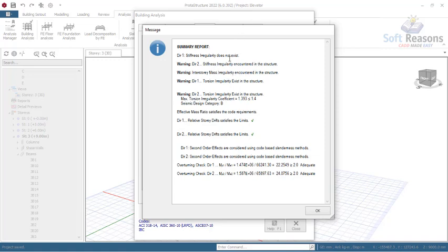Now, when you are seeing most of this warning, it is because of the way you model some of your structural members and how you incline them. As you can see in the structure, I have some inclined columns, right? Columns that are being inclined. So that is why you see this. This is just a warning trying to tell you something of that kind is in your model. So you have to take note of it and how it's being reinforced even at the construction site, so as to avoid unnecessary failure.